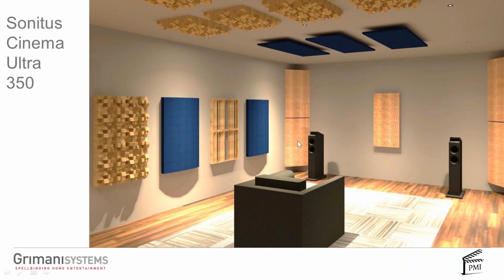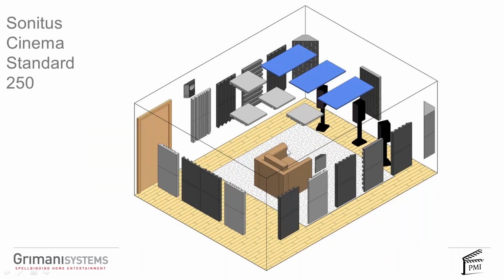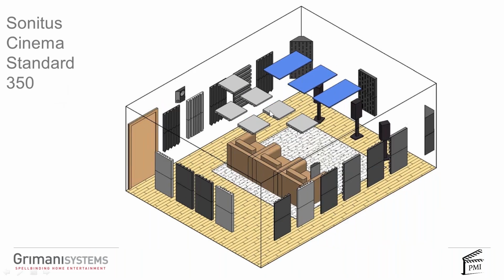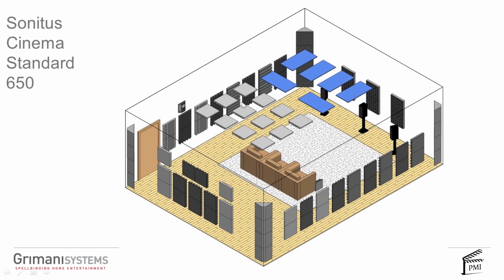And here you have absorption, corner absorption all the way up and down. Sure. So again, absorber interleaved in the room, 2D diffuser over here, 3D diffuser towards the back. Okay, these are diagrams that show the different packages. So we make packages for a 250 square foot room. For a 350 square foot room, there's just more treatments. For a 650 square foot room, just more treatments, but it is always the same guideline: 15% absorption, 20% diffusion.